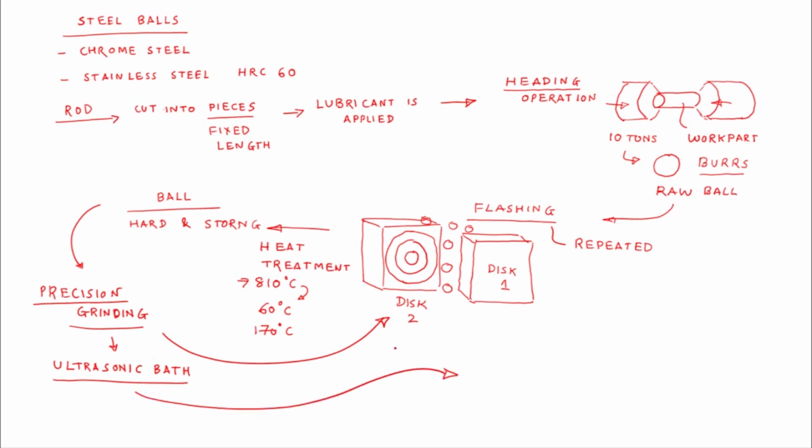After the ultrasonic bath of the rolled balls, inspection is carried out. It is expected that a ball of 16 mm diameter should withstand about 35 tons of load. These balls are inspected using optical equipment, and when there is an unusual reflection pattern from the surface of the ball, that ball is removed from the lot.